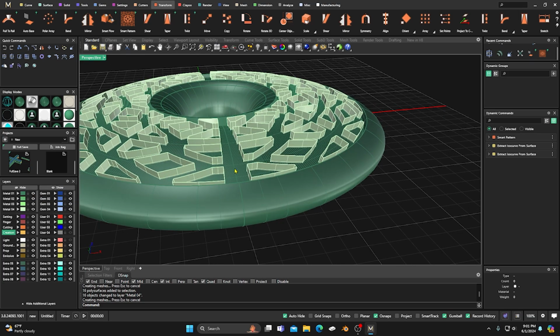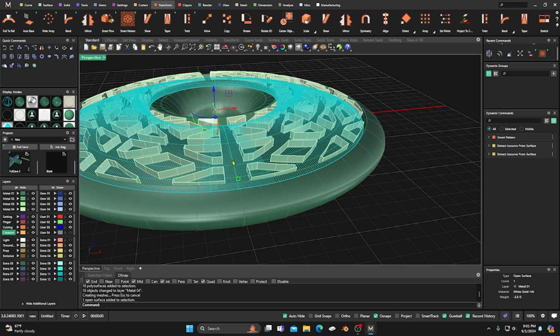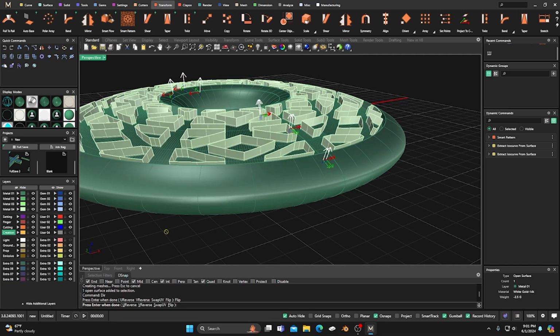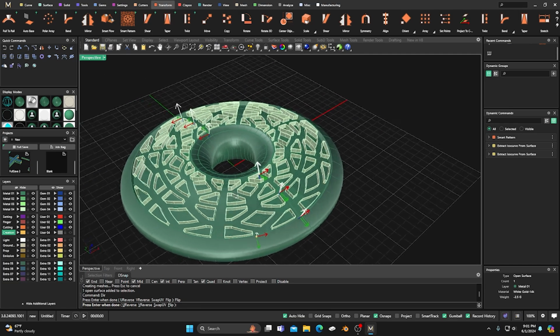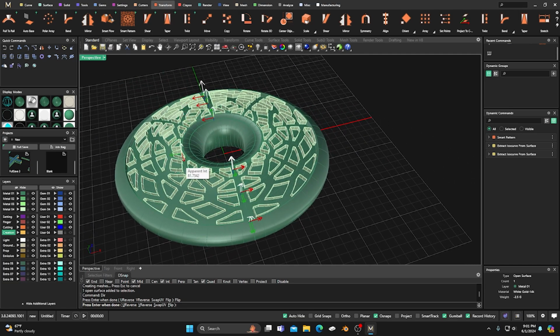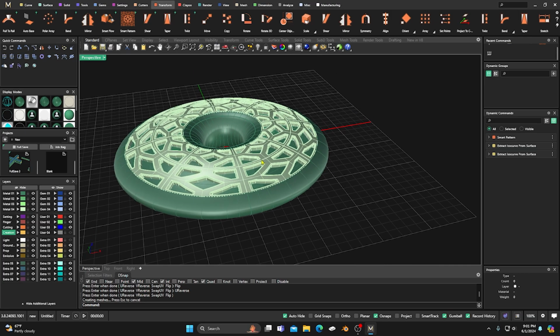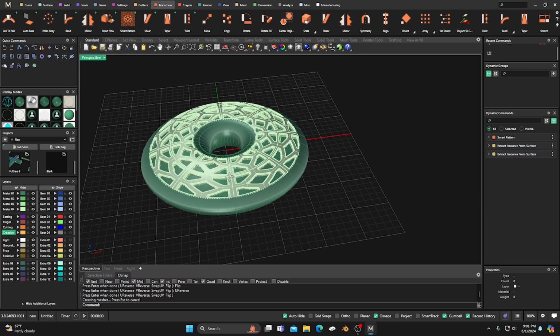So what we're going to do is select that surface again and type dir in the command line for direction, and you can see the normals are pointing down. The first thing we want to do is point those up, right? And the next thing we want to do is go in here and switch our red or U. So we'll reverse that, and then we'll hit enter. And now it gives us the correct surface facing up, right? And the open surface is down into the item.